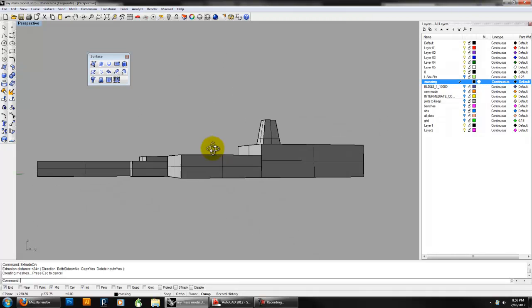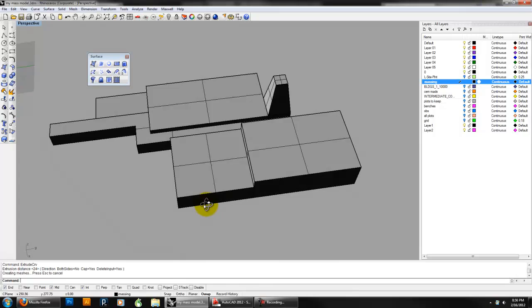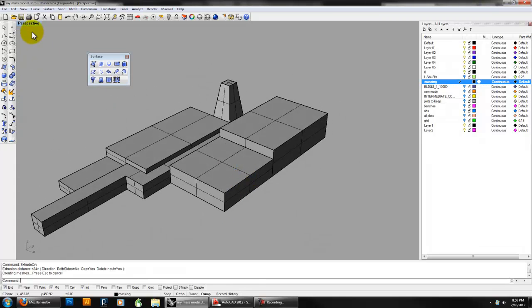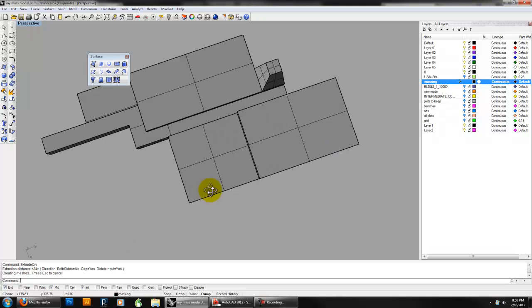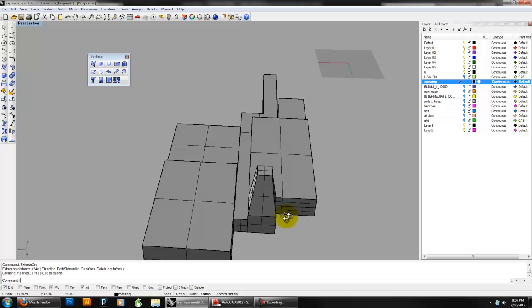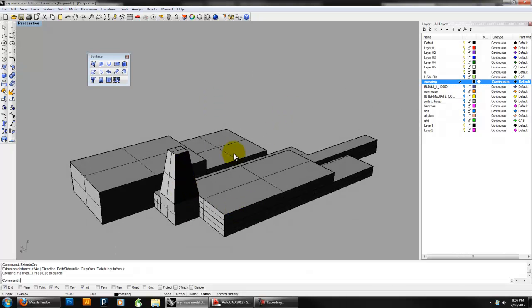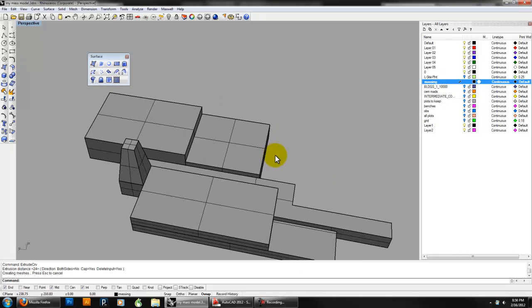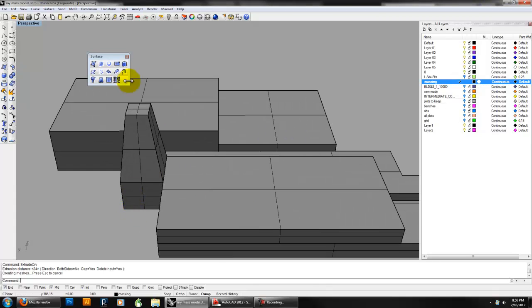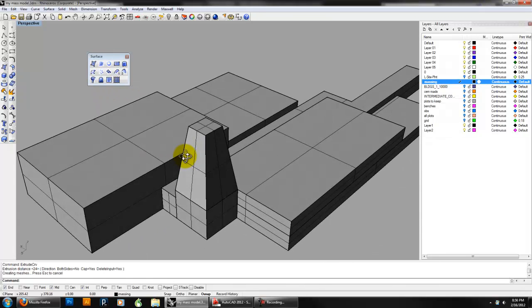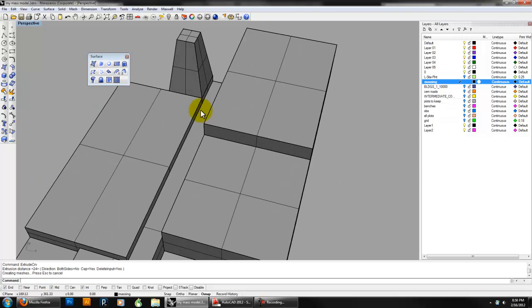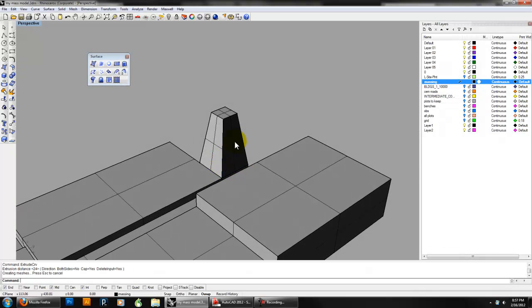So that is a very basic massing study of my building. And again, I just traced the lines from my building and extruded them using extrude curve. Here I did a little bit of complicated stuff to make this kind of smokestack, but that could just as easily be a really tall square or rectangular extrusion, and you could ask me later how to make a particular piece of geometry.